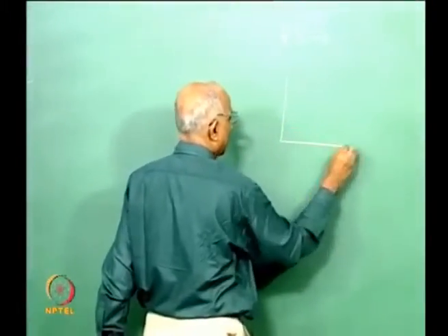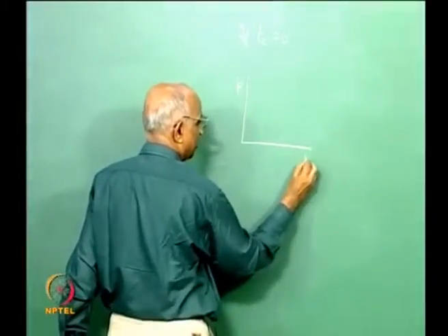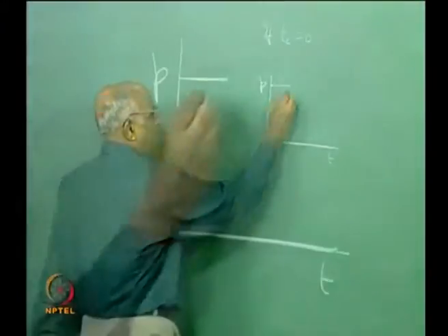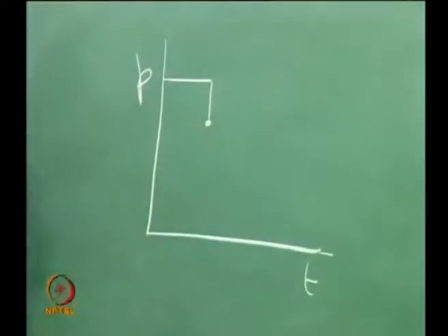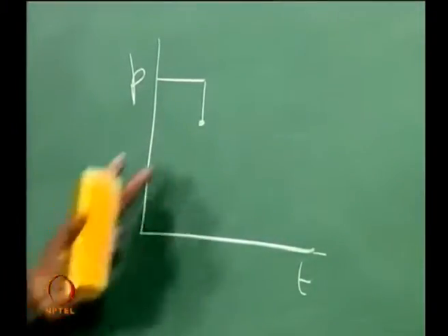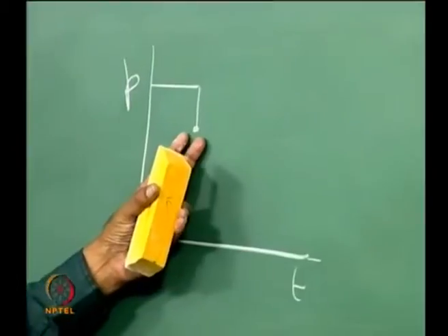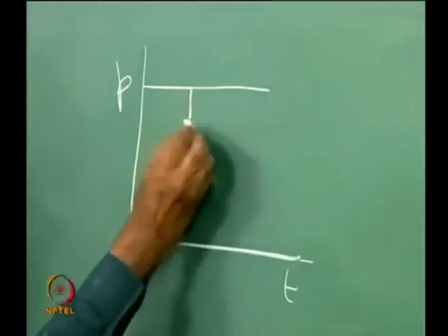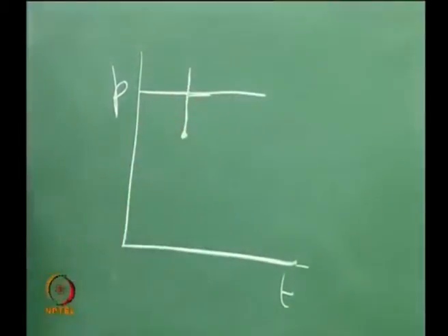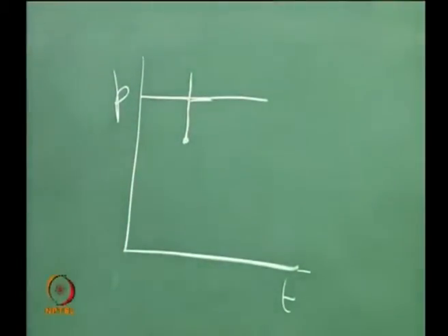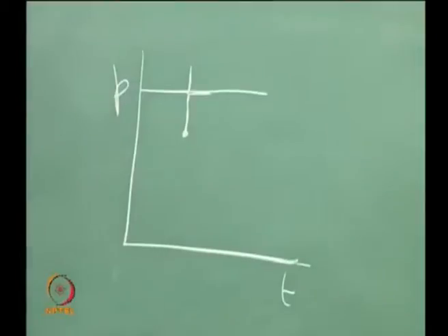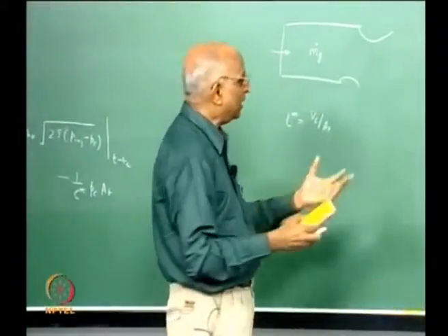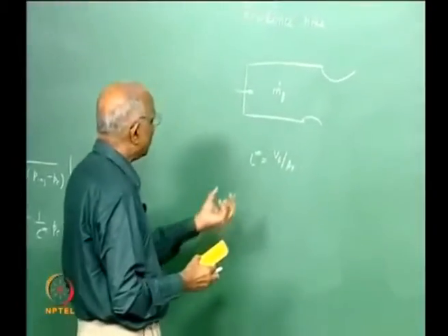Let me say, my chamber pressure with respect to time, originally I had 5 bar, it drops to 4.5 bar, but there is no time delay, immediately it burns and immediately it goes out. What is going to happen? It goes back here and adjusts, goes back here, adjusts. Therefore, without a time delay, I cannot think in terms of these oscillations. And what is the role of this time delay? Well, there is a lag and that is what causes it.